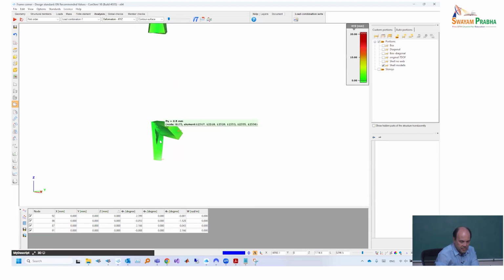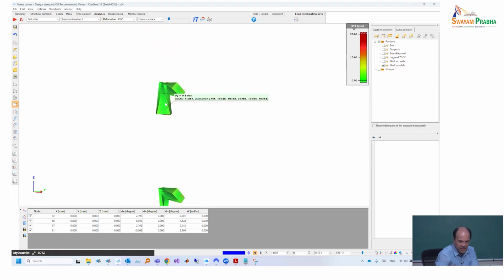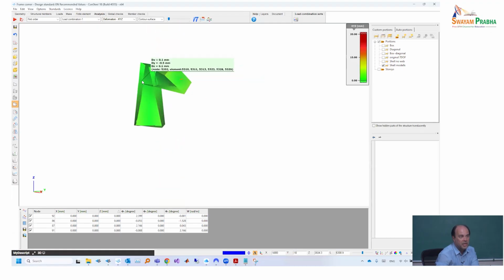And here what is also very important is that this can only happen with serious deformation of the web. So clearly in this zone, the beam element is completely crazy. It has zero validity. There is a very strong section deformation. It's not warping deformation, but really a very strong web deformation. So if I was able to describe this with a beam element, then I would need to employ such a beam element which is really able to describe web deformation. The 7-degree-of-freedom element cannot do such.